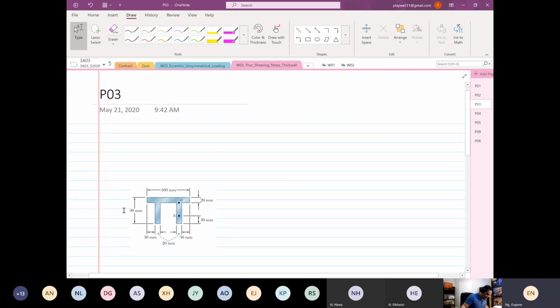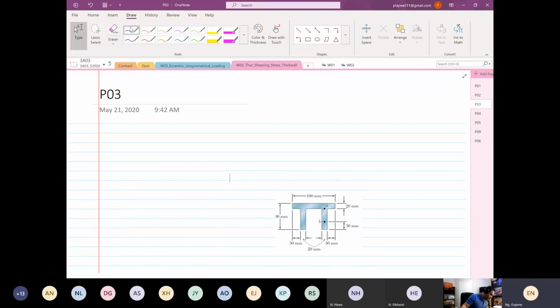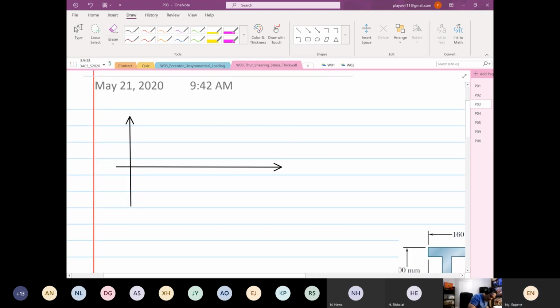So from here, we can construct our shear force diagram. Okay, so we're going to draw our shear force diagram. So this is X. This is V, and V is in kilonewton. And then we have 90 over here. Then we have minus 90. And then we have 0.5. And then we have 1. Over here is in meters. So our shear force diagram will look like this, okay?